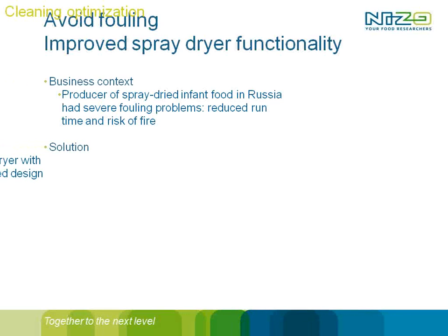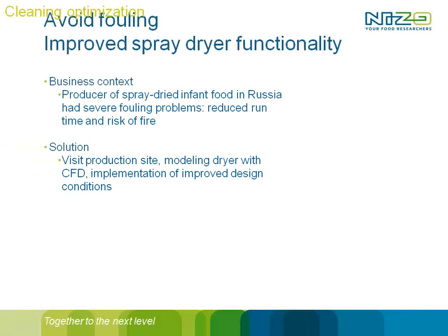We had a producer of spray-dried infant food in Russia, and they had severe fouling problems. And the fouling inside a spray dryer is actually a high risk. I mean, in a spray dryer, you have hot air, you have a powder, and if you have a small spark, you have the ideal ingredient for a bomb. It can explode, and that's something you don't want. So try to avoid the spark, since the hot air and the powder are necessary for your spray drying process.